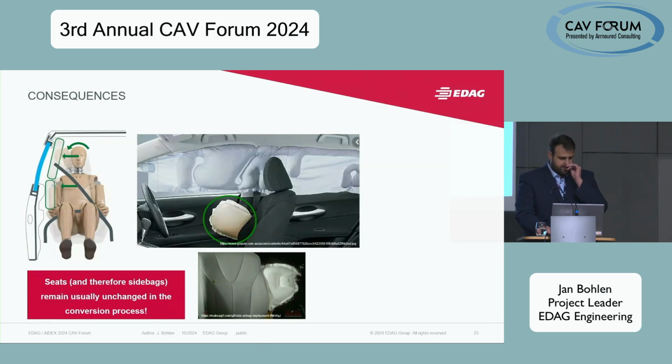Let's make a little mind game here. Let's imagine we have both of the airbags attached. We have a crash from the side. Our body wants to move against, or relatively against, the side wall of the vehicle regarding our mass of inertia. So we have the possibility to lean on the side bag and then lean on the pillow to prevent the contact with the rigid structure.